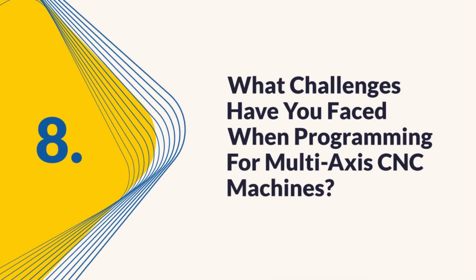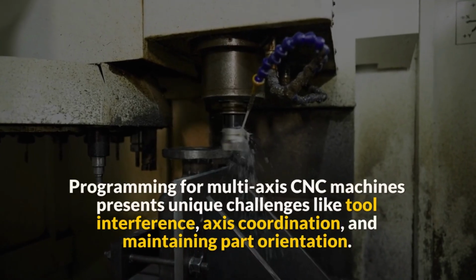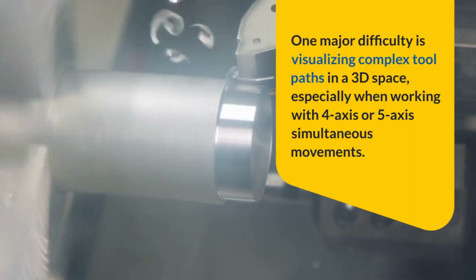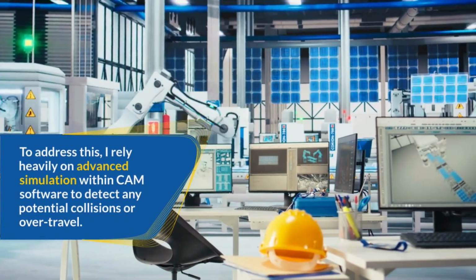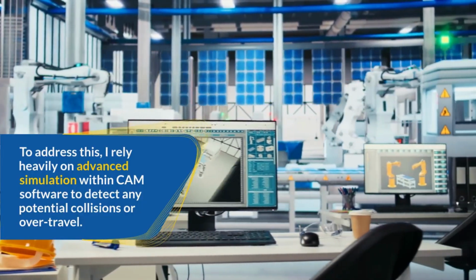8. What challenges have you faced when programming for multi-axis CNC machines? Programming for multi-axis CNC machines presents unique challenges like tool interference, axis coordination, and maintaining part orientation. One major difficulty is visualizing complex tool paths in 3D space, especially when working with 4-axis or 5-axis simultaneous movements. To address this, I rely heavily on advanced simulation within CAM software to detect any potential collisions or overtravel.